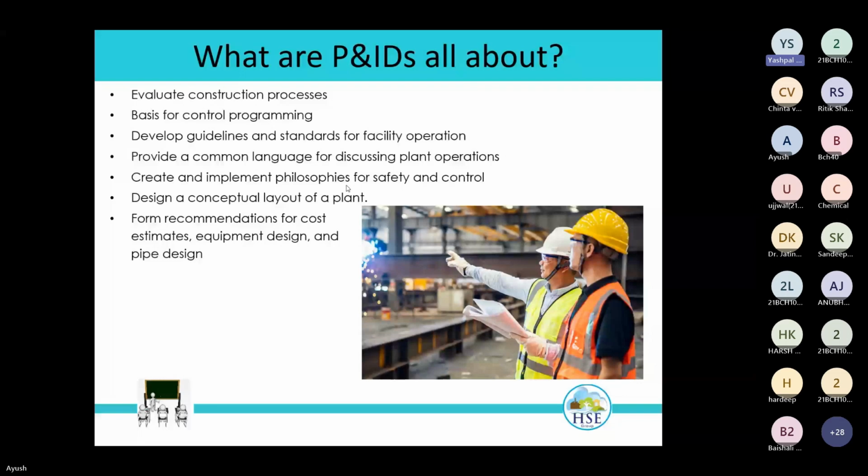And normally during the process of project, we have designing, then installation, commissioning, and then operation. So before commissioning, commissioning team and operation team should have the process details, SOP and guidelines. So standard operating procedure, sorry, operational procedure and guidelines that normally we develop with the help of the P&ID. So this way P&ID is helpful to us even in developing the controls and logics.